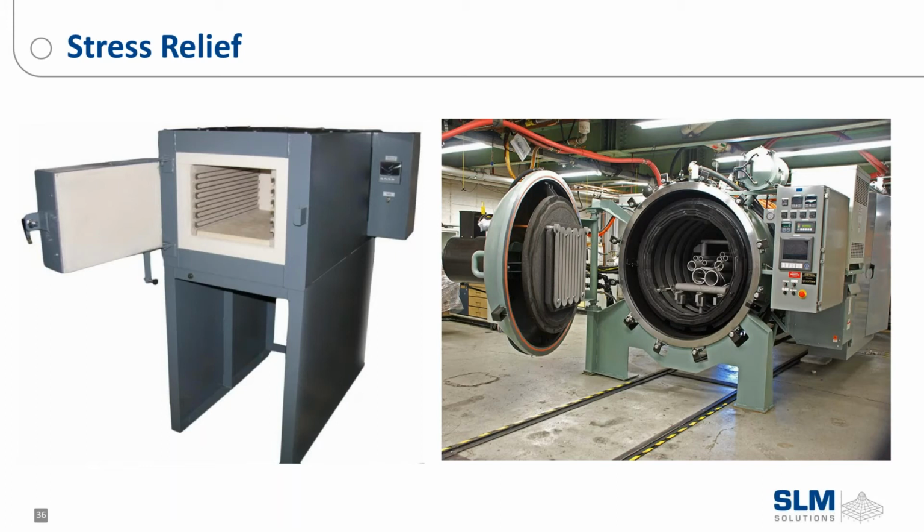Also, CMM inspection. In the top right, we have a handheld CMM. This is very useful for scanning material and checking outside dimensional accuracy of parts. And in the bottom left-hand corner, we have a Keyence VX series microscope. We use this for looking at density samples and metallography samples.